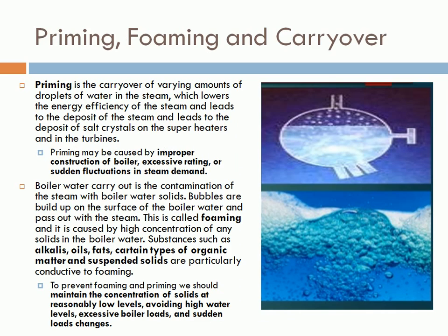So what is priming, foaming and carryover? Priming is a carryover of varying amounts of droplets of water in the steam, which lowers the energy efficiency of the steam and leads to the deposit of salt crystals on the superheater and the turbines.